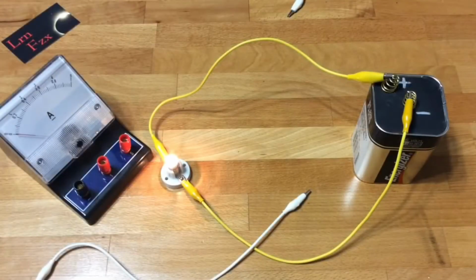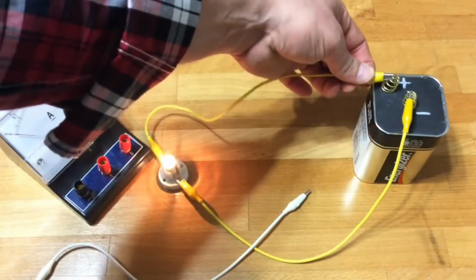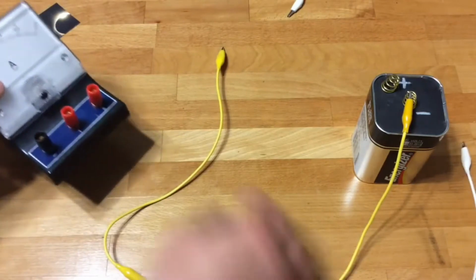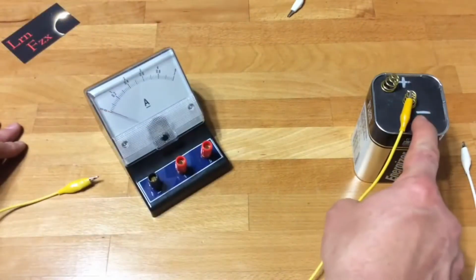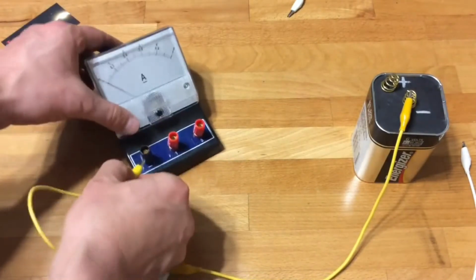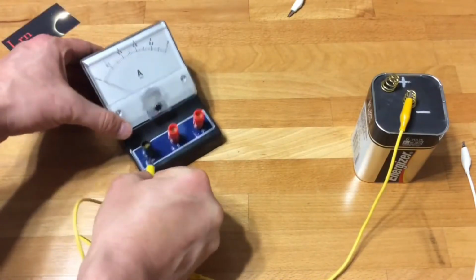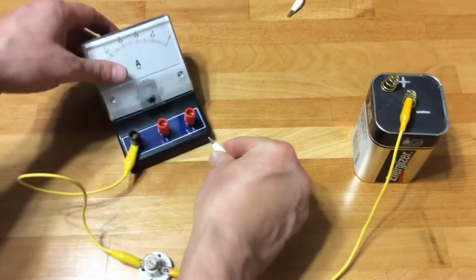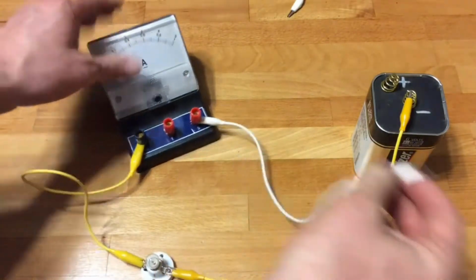Starting with this basic circuit, 2 wires, bulb, battery. Let's say that you want to measure there, the current flowing at that point. Disconnect at that point, place the ammeter in between the 2 points that you disconnected, and reconnect. Negative of the ammeter should be on the negative side of the battery, positive of the ammeter on the positive